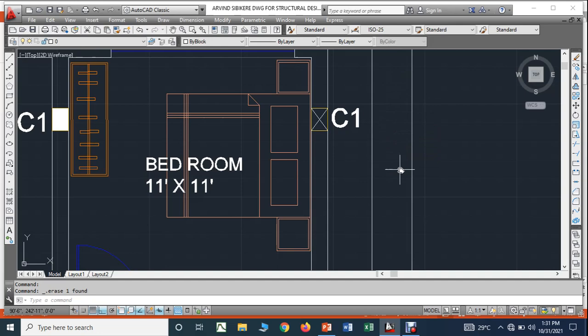Another important reason why you are supposed to give the setback is, you can see here, if this is the boundary, another building may be here. If you skip the setback, there will be a problem with privacy. Two residential buildings, or any two buildings, if they are very close, will definitely create a problem of privacy.